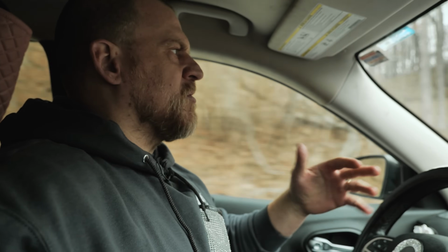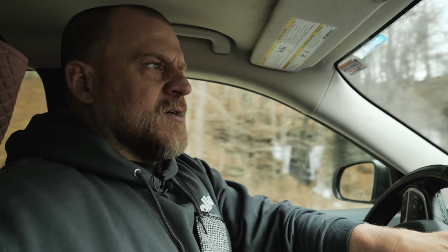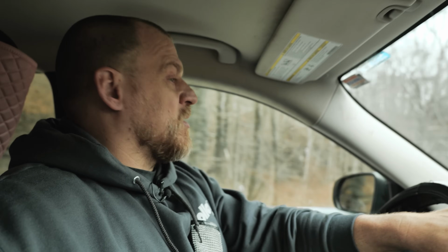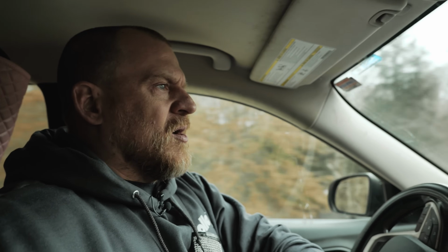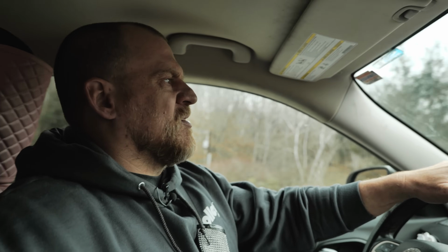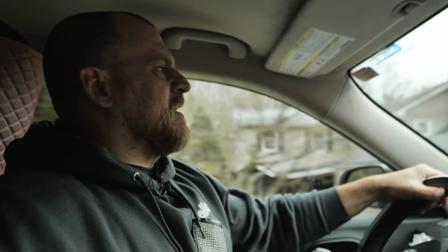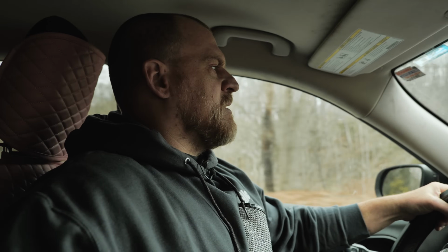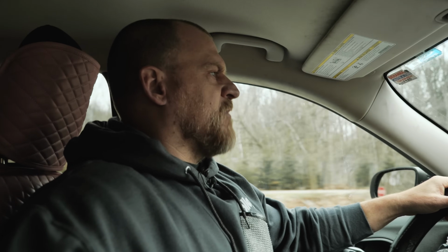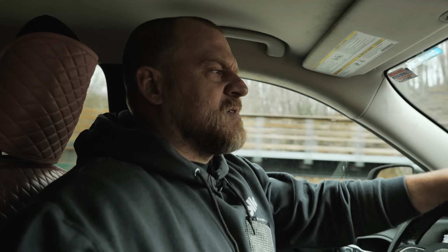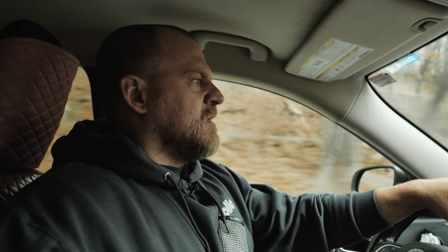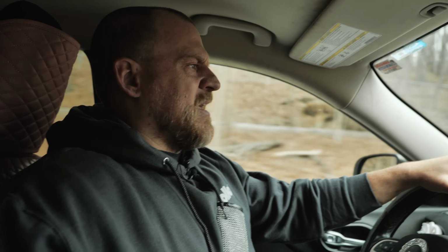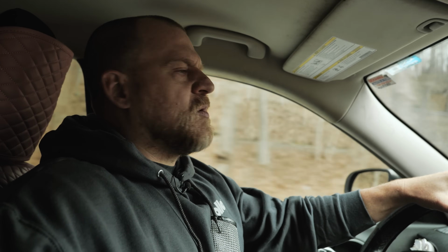We have an intermittent problem. What I didn't look at on the freeze frame data was what engine temperature we were at, but we were under load when the condition happened too, so that moves me away from a vacuum leak too. And to restate, vacuum leaks on intake gaskets don't fix themselves. Well, there is a variable to that: temperature. They can seal up, like leak only when they're cold.